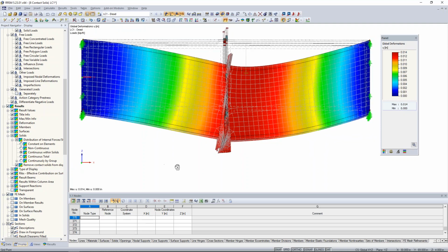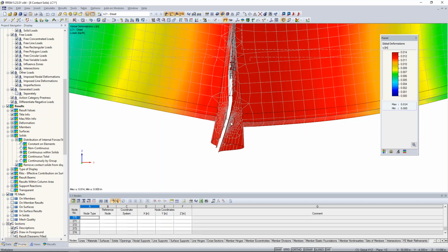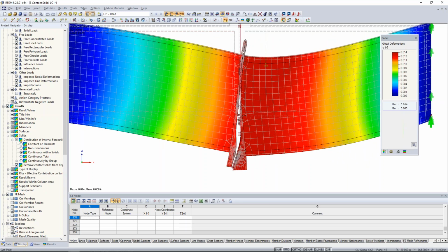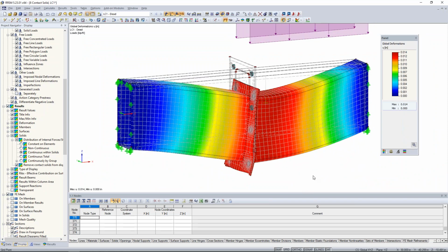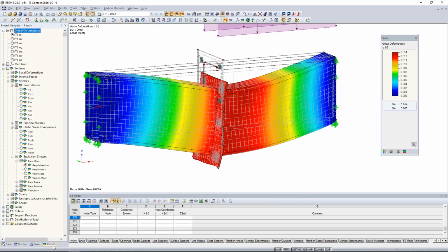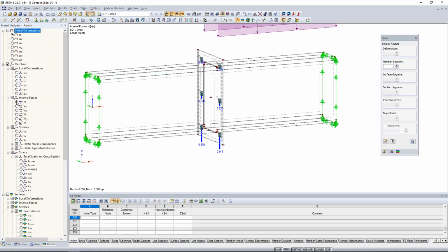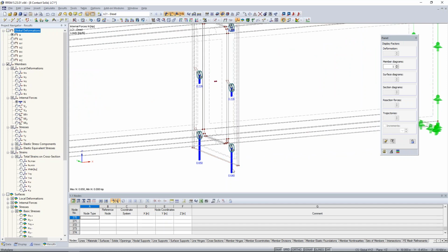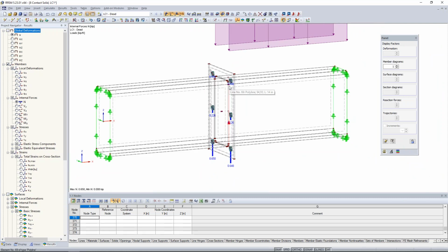So when we're looking at the deformation, it's quite apparent where our plates are failing in tension, and those bolt elements are holding those two elements together. But up here at the top where we have compression, we can see those plates acting together because they are working with full force transmission. Under the results tab, we can expand out the members option and actually view the tension forces as the normal axial load in these small bolt elements. And as we'd expect, we have a higher tension load for those bolts at the bottom, and as we move up the plate, a much smaller tension load, if any.